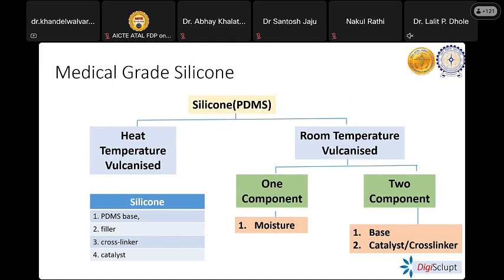This is one of the 3D printing techniques, where a freeform reversible embedding technique is used. Here the bed is a viscous silicone material where the syringe extrudes a cross-linker into it, and this material itself supports the main structure during the 3D printing. So this is a kind of freeform reversible embedding, where a well of viscous material, which is the base, in this case polydimethylsiloxane, and then the cross-linker is extruded with this extruder head, and the 3D printing is done.